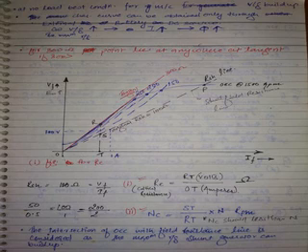Now, somewhere here you will have a point. Don't worry about this line because they are proportionally, linearly varying. The length between this and this are linearly varying. If you take this point or this point or this point, it will be the same value because it is linear. So this is cutting OCC here, you make it a point here. Carefully observe. What is this point? This point is on the shunt field resistance line.